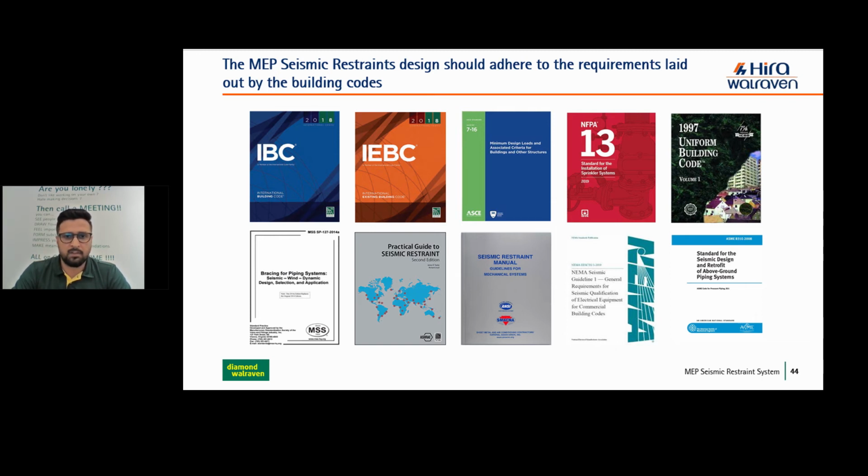Sometimes you have rigid system bracing, and then the seismic restraint manuals from SMACNA can be applicable. The practical guide to seismic restraint from ASHRAE is a summary of all the different standards. And for electrical, we have different design references, and these can all be useful to design any seismic system.